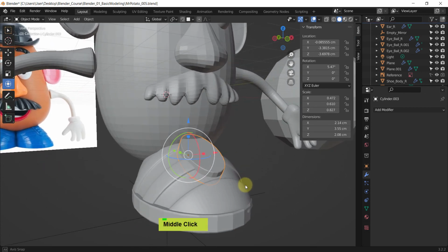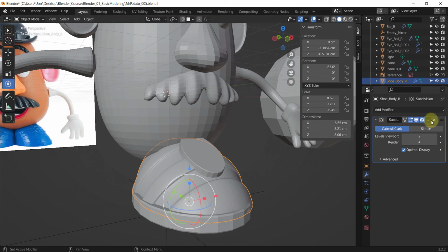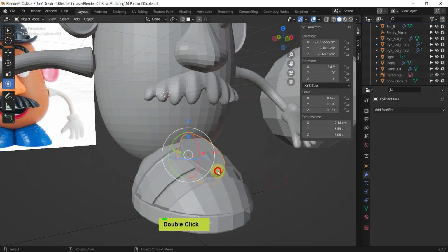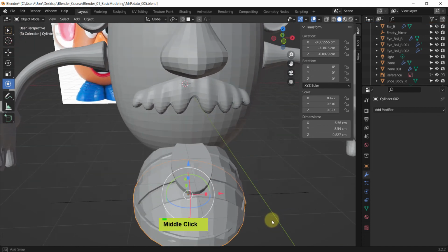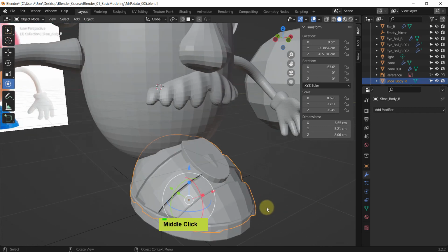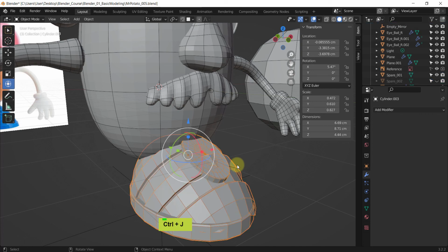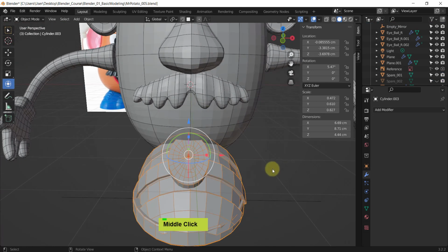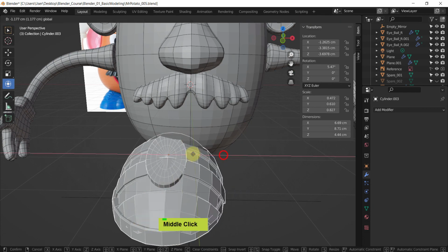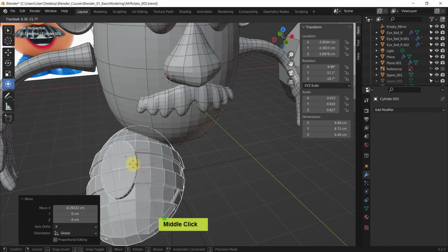And to make sure that everything is working as one unit, I can actually remove the temporary subdivision modifiers. Here we don't have any, here we don't have any. So what we can do is join them. Select this one, and this one, and Ctrl J to make them one single unit, and then move it away and rotate it according to the needs.